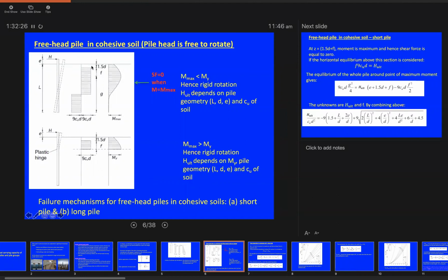You can either work out the solutions from first principles of static equilibrium by forming the equations, and the equations you can form here either from the sum of the horizontal forces on the system or the sum of the moments on the system.